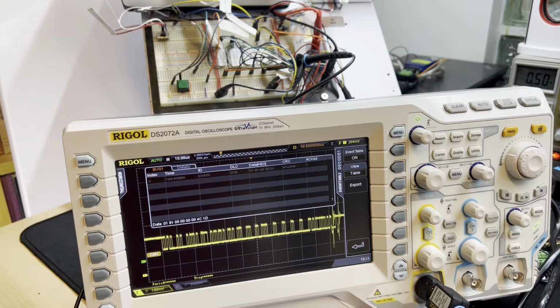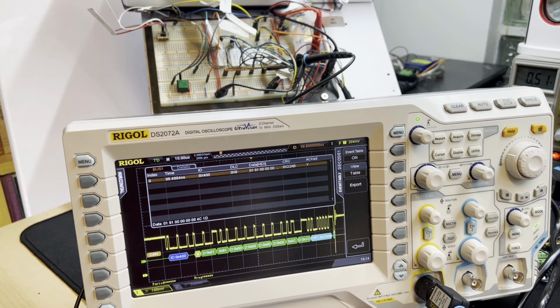Every CAN bus must have at least 2 nodes, with the transmitter being notified of correct transmission by the acknowledgement sent by one or more actively listening nodes on the bus. It is a common beginner mistake to try to build CAN buses with just one node for testing. Also beware that nodes can be configured to behave like this oscilloscope and merely listen on the bus without actively acknowledging transmitted messages.